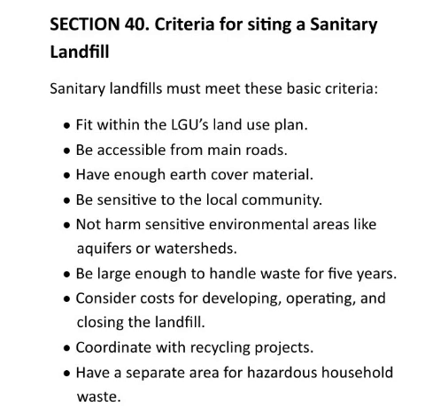enough earth cover material, be sensitive to the local community, not harm sensitive environmental areas like aquifers or watersheds, be large enough to handle waste for 5 years, consider costs for developing, operating, and closing the landfill, coordinate with recycling projects, and have a separate area for hazardous household waste.